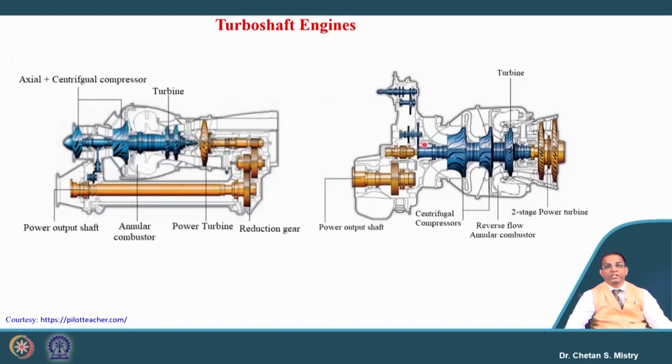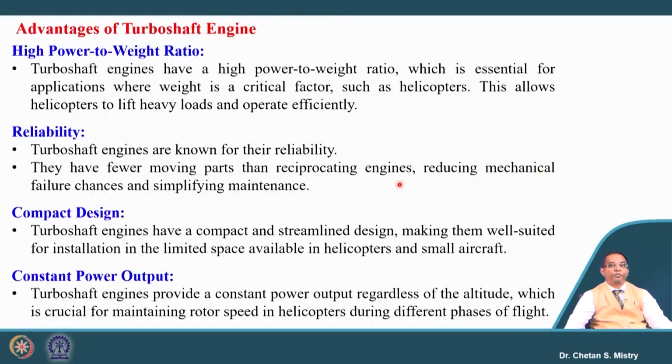Similarly, here in this case we have two centrifugal compressors followed by this turbine. This turbine mainly rotates these two compressors. On the back side we have the free turbine. This free turbine has a shaft going inside, and that is connected with the power output shaft.